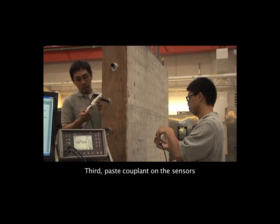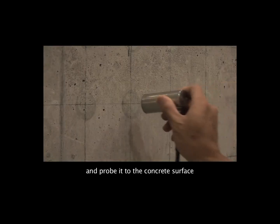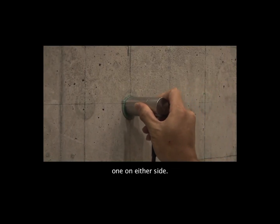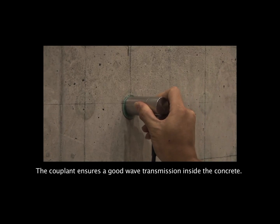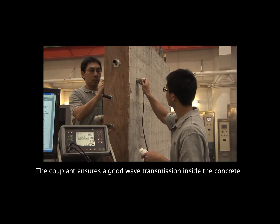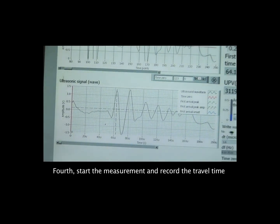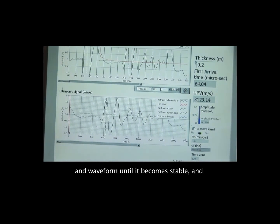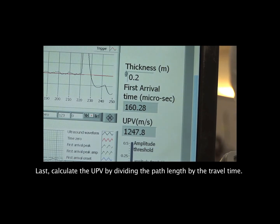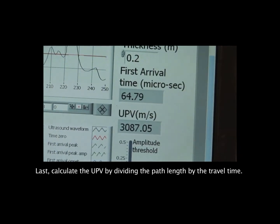Third, place couplant on the sensors and probe it to the concrete surface, one on either side. The couplant ensures a good wave transmission inside the concrete. Fourth, start the measurement and record the travel time and waveform until it becomes stable. And last, calculate the UPV by dividing the path length by the travel time.